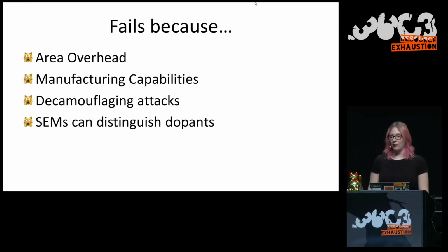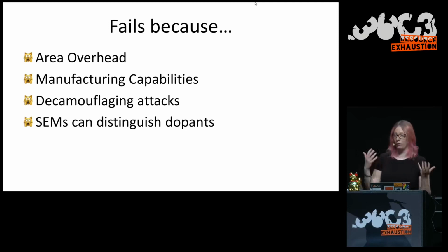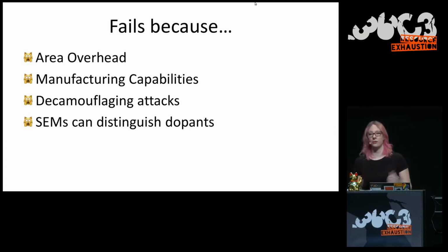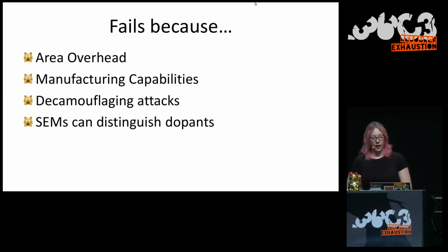In the past, there have now also been published some decamouflaging attacks. They're also based on what would be normal to have in a kind of chip, and to try to reverse engineer the functionality there, or even to brute force it, because you know this can only be a NAND and a NOR. Well, that's two options. Let's brute force that.